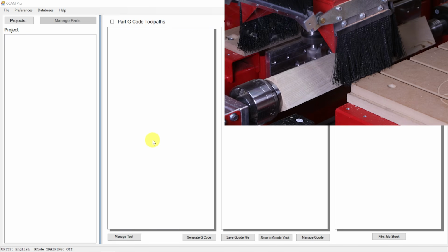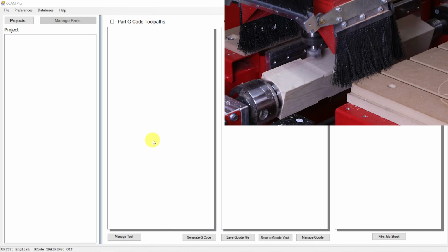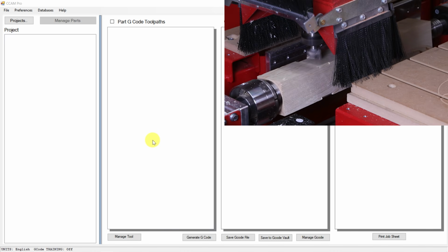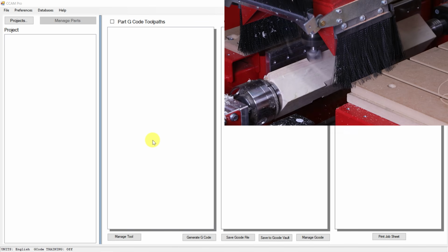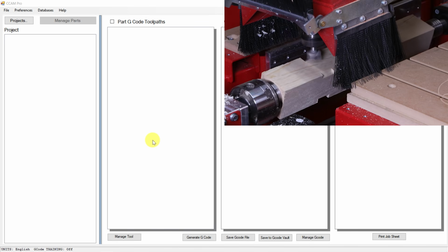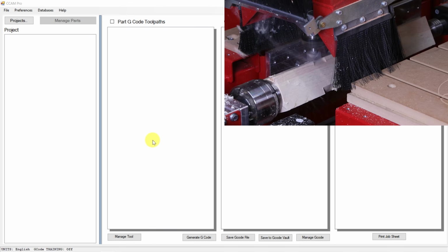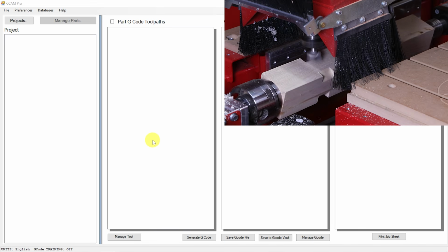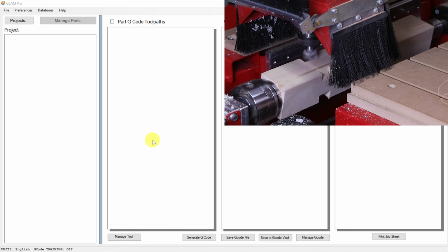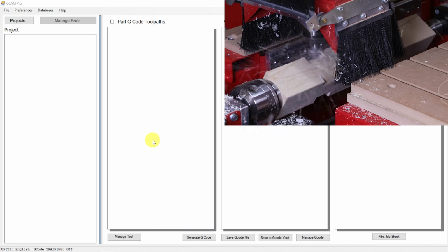This one, the turning round, I'm going to call a core or foundational toolpath that you're going to be using. Almost guaranteed that you're going to be using this toolpath in almost every single spindle that you're going to program. It's also critical because this toolpath will be one of the first ones you implement into your actual part before other turning procedures, because they're going to be asking what turn round cylinder you want to place these on. So this is what's going to perform the actual turning round sequence as the original process.